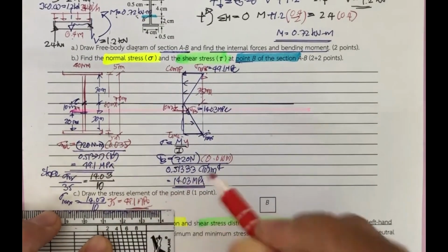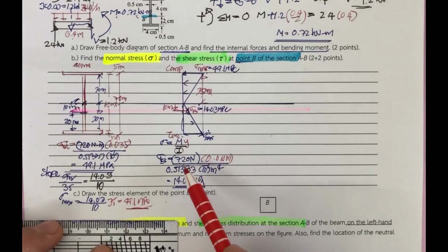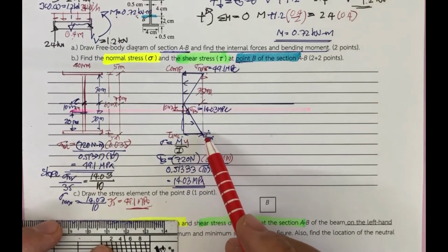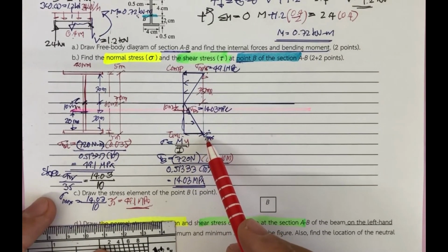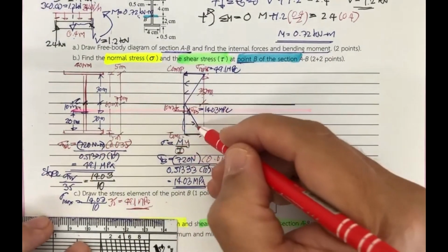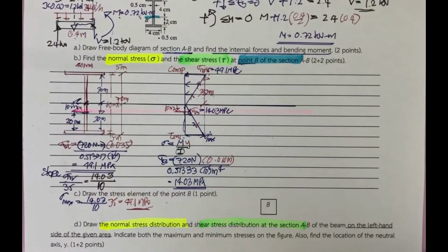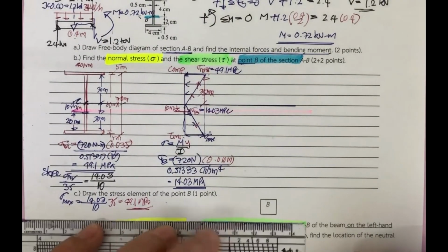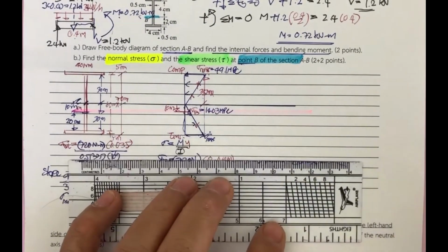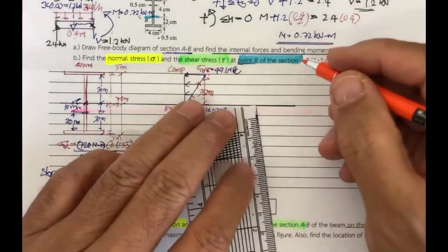So the value of stress can be determined first by the flexural formula, and then, because the other points are in a triangular distribution, you can use the slope to determine the stresses at the other points if you would like. It's really easy and convenient to do so, right? Okay, and then you have to consider the transverse shear stress by doing this.